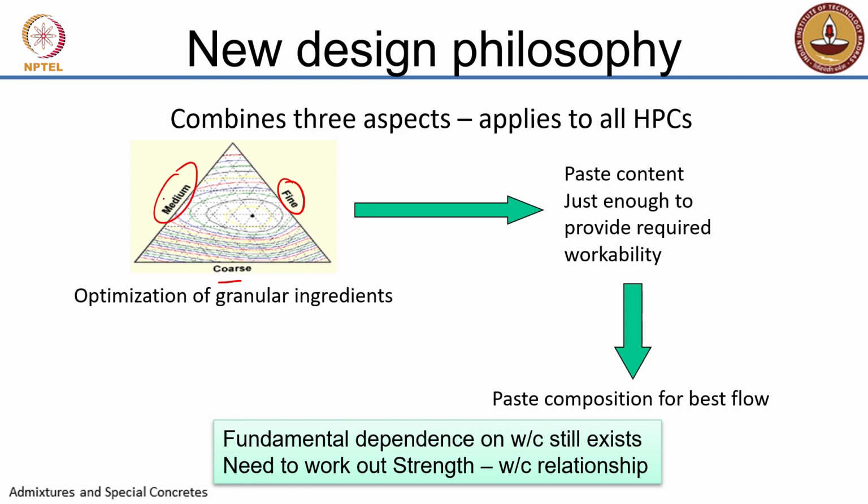So you can, based on your understanding of concrete mixture design, arrive at a lesser number of combinations of the ingredients to get you the desired voids content. Nevertheless, it has to be an optimization exercise. This is, of course, a much more sophisticated exercise where contours of equal packing density are plotted, right? I'll discuss what is meant by packing density later. And then there is a single point at which you get the maximum packing or minimum void content of your mixture. Okay.